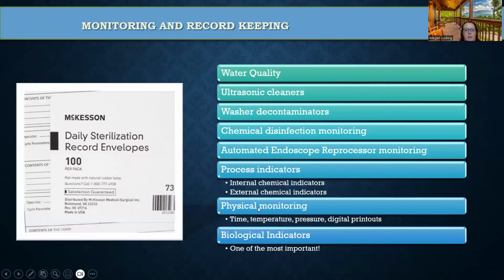And then you're always going to have this physical monitoring for all of your sterilizers. That's going to be your time, temperature, pressure, and usually you can have a little digital printout that might go with your record.